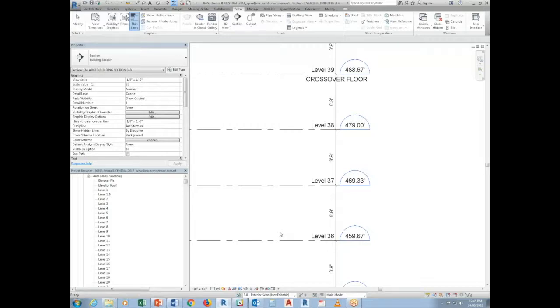So it's a good idea to create them up front. If you know that you're going to be using area plans, let's say gross building or saleable, and ceiling plans, then just create all the views simultaneously, just to prevent people from renaming stuff. Okay, and then I treat these as the working views. People can just go in there, look at this, and copy stuff, and it makes it a little bit easier for them. So you no longer have to create a bunch of working views.